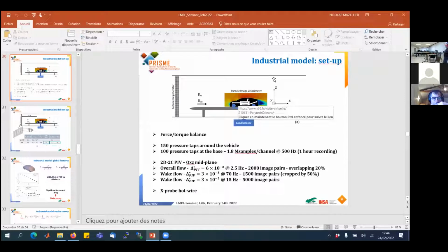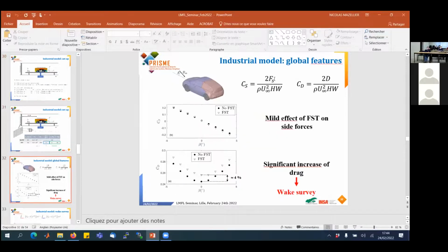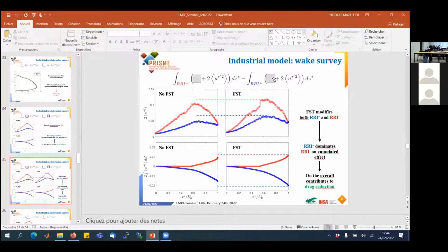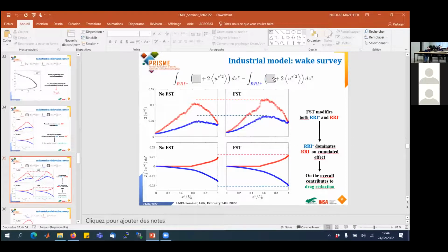Well, maybe I can ask a question then. I'm going to ask a question about things that you said you wanted to talk about. You said that with your hybrid LES method you have a much better agreement with the experiments, and also you wanted to run the simulation long enough to see extreme fluctuations or bistability. Both of them. And the question is how performant is this method, which is not DNS, to represent maybe the bistability event that you would also have in experiments? Do you have an agreement between the two, at least qualitatively, between experiments and simulation?